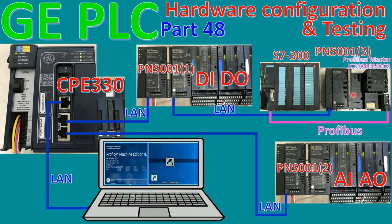Yes, that links with Profinet I/O, linking to the PLC S7-300, and I will link data from PLC GE to PLC S7-300 and link data from PLC S7-300 to PLC GE.